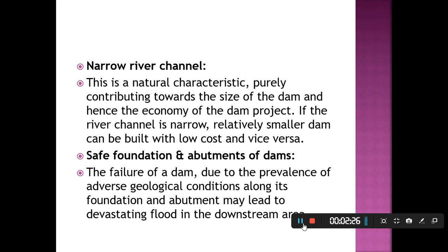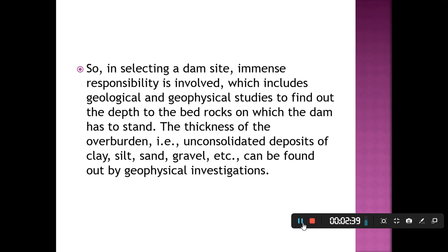The failure of the dam due to adverse geological conditions along its foundation and abutment may lead to devastating floods in the downstream area. So, in selecting a dam site, immense responsibility is involved, which includes geological and geophysical studies to find out the depth of the bedrock on which the dam has to stand. The thickness of the overburden, that is, unconsolidated deposits of clay, silt, sand, gravel, etc., can be found out by geophysical investigations.